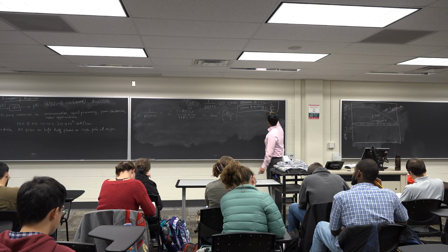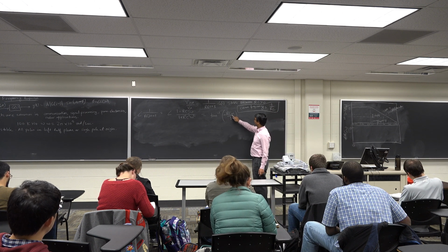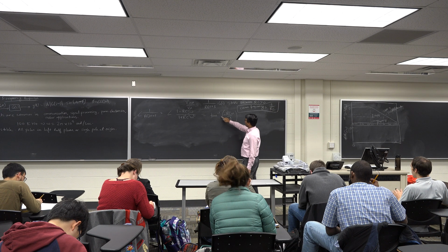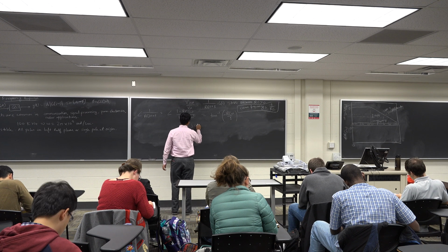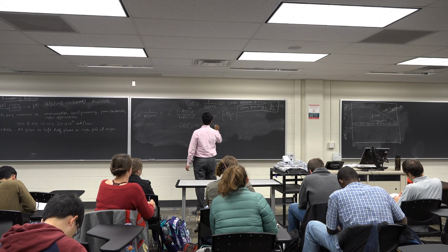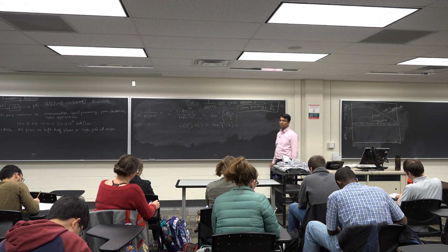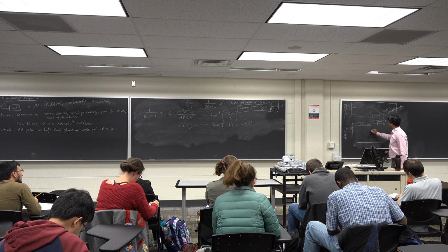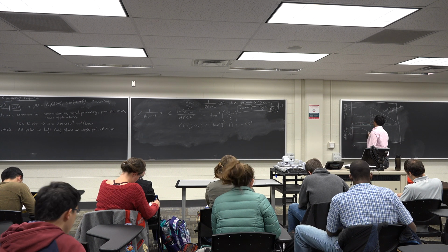What happens when omega is 1 over RC? So at the corner frequency, what happens to tan inverse? At the corner frequency, omega is 1 over RC. This is tan inverse minus 1. Anyone remembers what tan inverse minus 1 is? Yeah, minus 45 degrees. So at the corner frequency, this is minus 45 degrees. So you reach here.